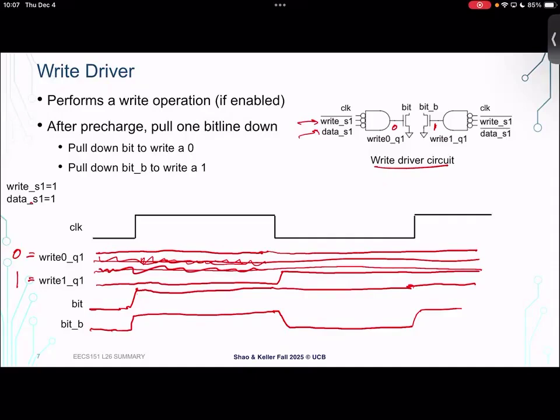This is the condition we have. Those are going to start, or we can assume that they're low or that they're off to start. And in particular, they're always being driven to 0 when the clock is high, right? Because we have these clock inputs to the AND gate.